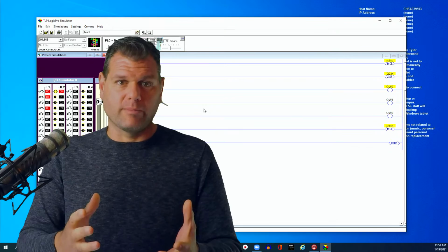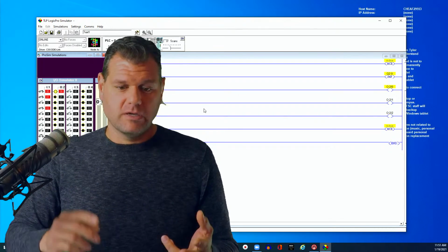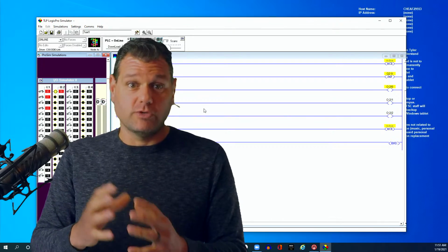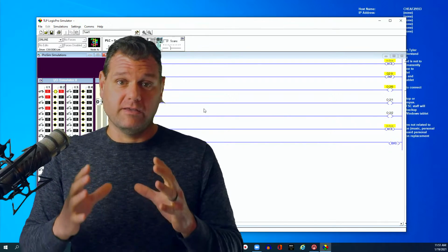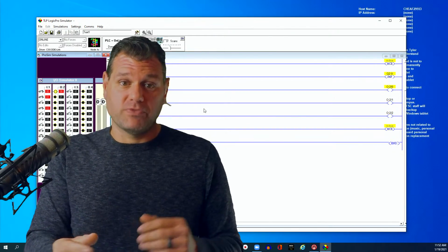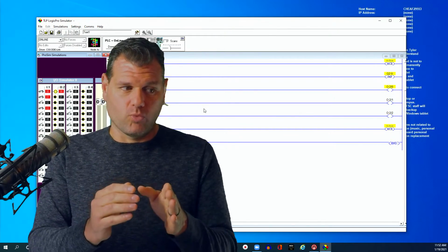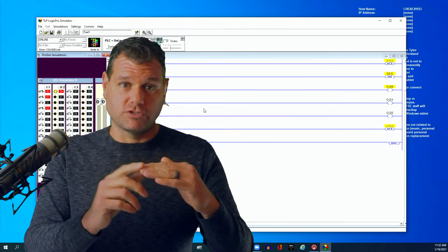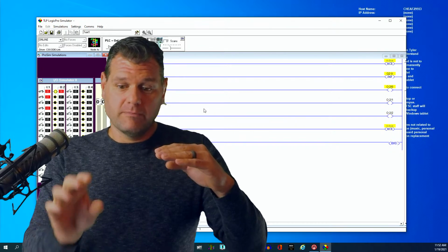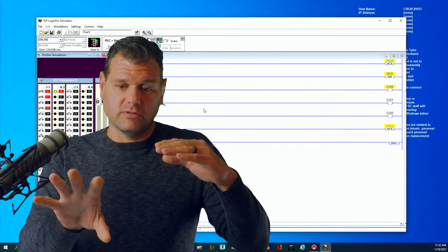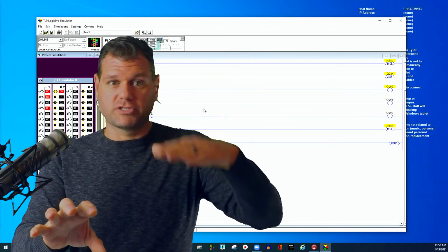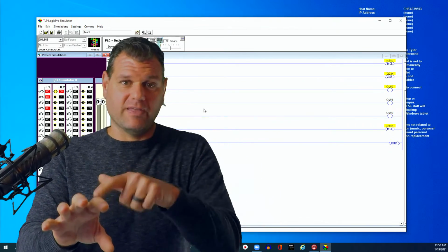The main program is typically going to be your safety systems. It's going to be your motors. That's another thing. You can, but try not to put any outputs in a subroutine. The reason being is like that scenario earlier. When my temperature was reached and I went to start the burner, if my output was in the subroutine itself, I would turn the burner on, and then when the temperature is reached, this rung is going to go false, and I'm not going to scan that no more.